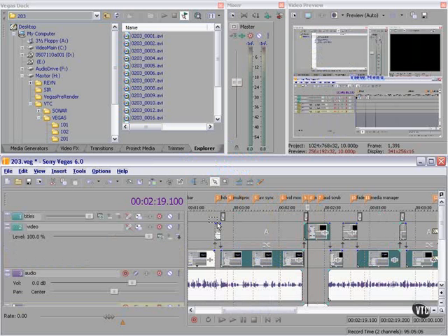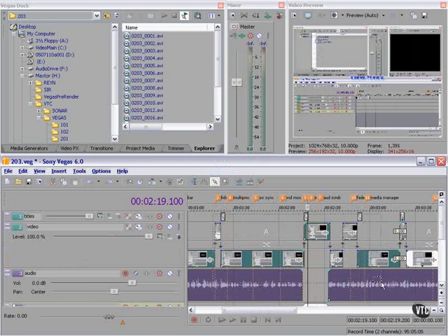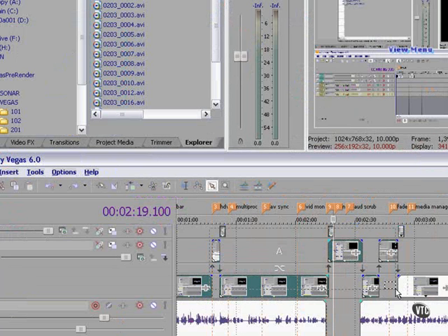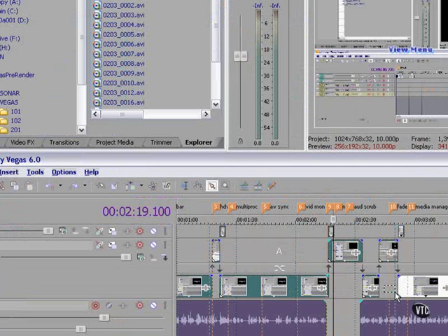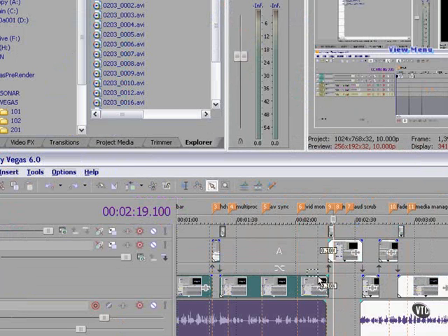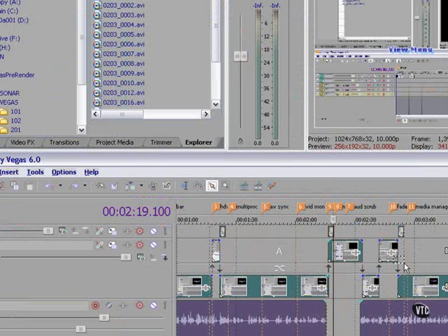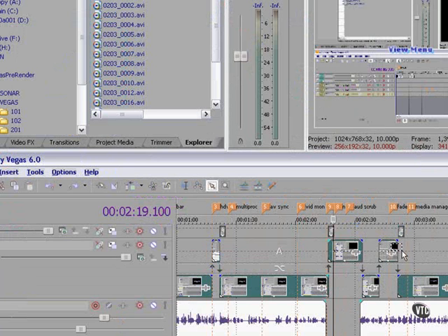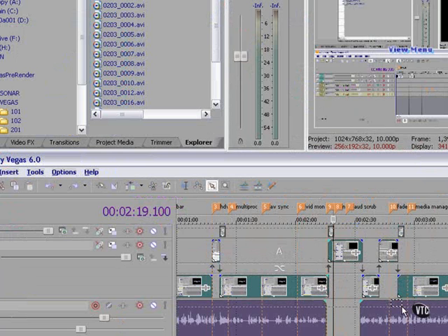This is the Selection Edit tool. Use the Selection Edit tool to select events across tracks. Notice that it creates a rectangle, a little box there on the right. Can you see it? If, while holding down the left mouse button, we click the right mouse button, we can constrain this to the vertical direction. If we click again on the right mouse button while holding the left mouse button down, it switches to horizontal selection. And if we click once again, it goes back to normal.